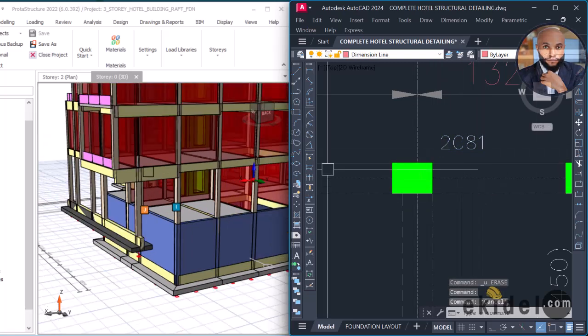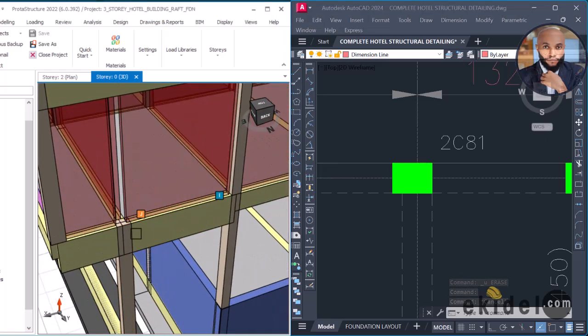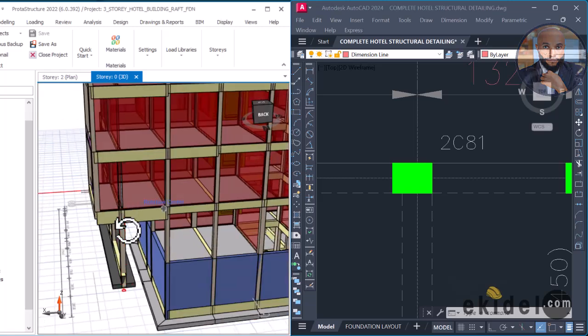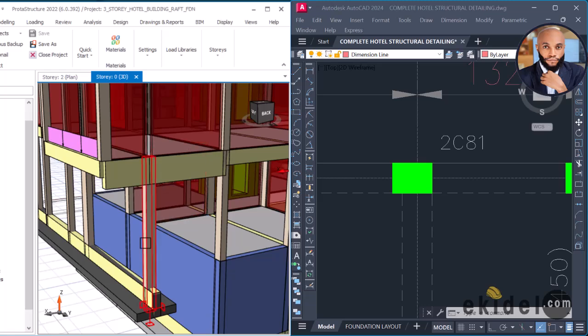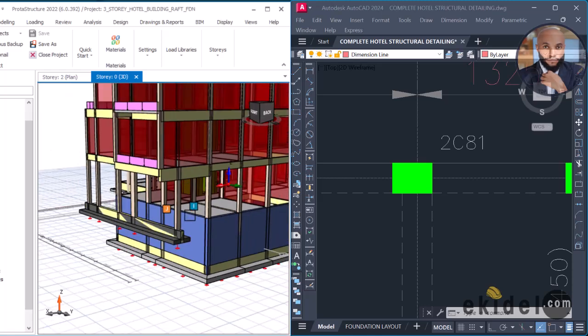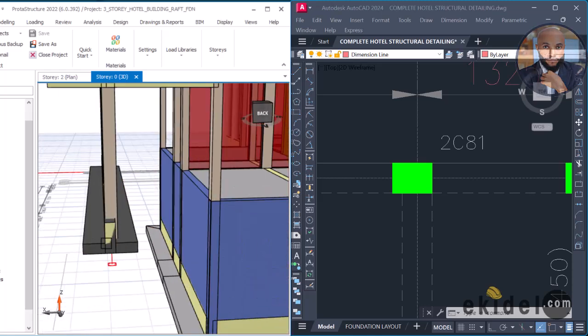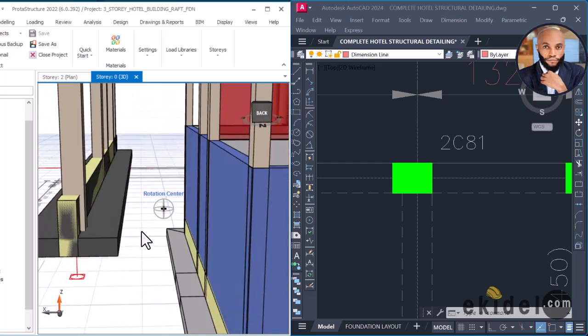And from the view here, if you look very well, you can see that this column is only on the ground floor. All right, so it terminates directly at this slab here and does not continue. And the beam at the top here is 750. If you can see that right now, 750 depth of beam, which is H at 750. Okay, that's fine. And also it is sitting on a strip foundation, as you can see right now, which is like a T.